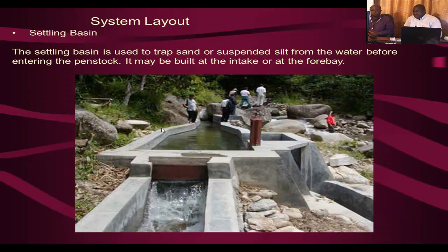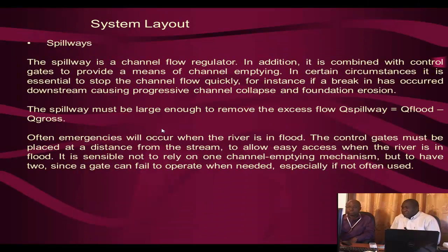Settling basin. You will require a settling basin to trap sediments or suspended silt in the water before entering into the penstocks. It may be built at the intake or at the forebay.